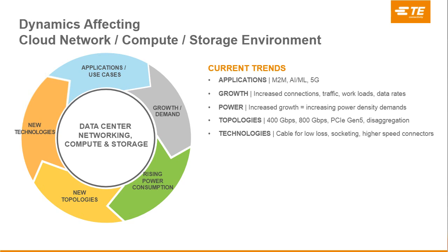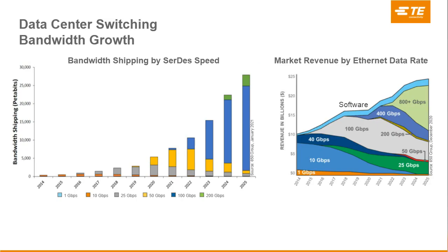We have to improve the performance to meet these speed requirements across many different products. Today, the industry is transitioning from 56 to 100 gig. And what this means is, characteristics like insertion loss and return loss, and crosstalk, these are all things that we care about, but now the frequency that we care about them increases. So instead of 12 gigahertz, now we're increasing that to 28 gigahertz and even higher.